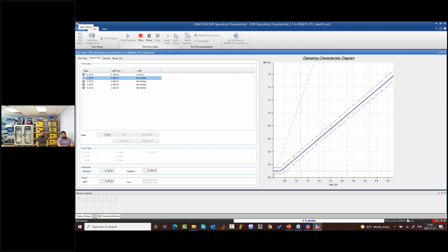You can't hear anything because it's not injecting. It's injecting sample values. This is a new feature with the new software version, because before we had to generate analog at the same time with the sample values. Yes, exactly. Now we can publish 3 streams. And you can see binary input 1 is triggering. It means that there is a trip command. Maybe they can see it in the trip time, which is coming up.